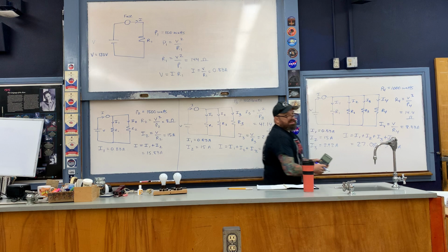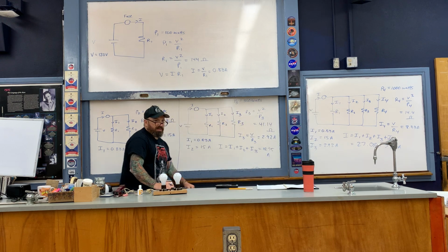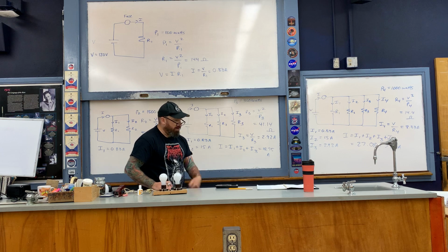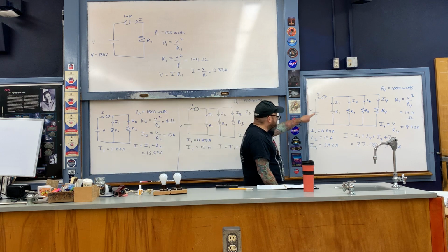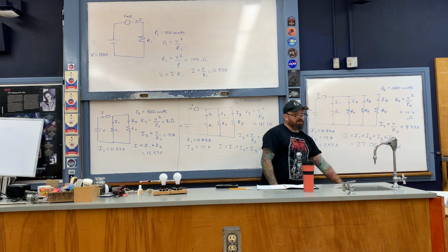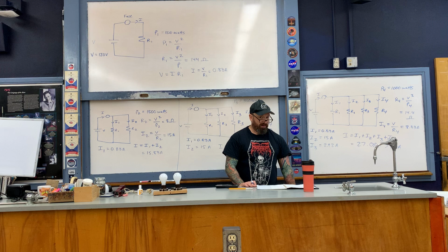So this is dangerous. Because this is dangerous, the fuse that you have placed in series with all of this is good. Because at this point, for example, this small piece of metal here would melt. When it melts, it breaks the circuit and everything turns off and nothing catches on fire.